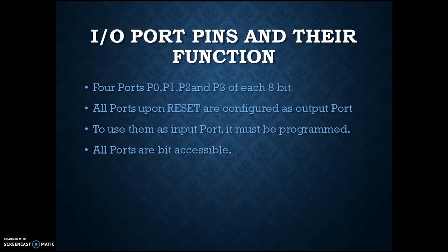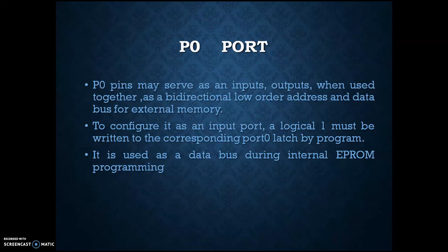Now this P0 port we will discuss in more depth. P0 port may serve as inputs, outputs, and when used together, if you can remember the pin description of the 8051 microcontroller, as a bidirectional lower order address and data multiplexed bus.